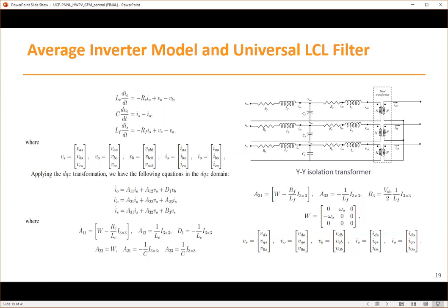There, we either have the average model, which assumes the voltage right after the switch is proportional to the DC voltage, or the HW model. Any other type of EMT model, due to the lack of analytical representation, is very hard to use for real-time control. And that's part of the reason we're also doing the HW model. And more on that later.